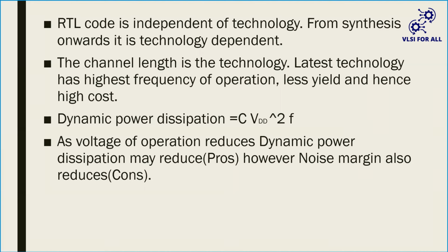So specifically, the noise margin must be maximum. Even in CMOS, it is maximum when compared with PMOS and NMOS. That is also one added advantage of CMOS. So when you go for lower voltages, the noise margin reduces, which is a disadvantage. Hence, in every design, reducing the voltage is not the permanent solution regarding dynamic power. Okay, that is also one of the points, team.